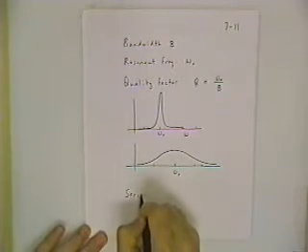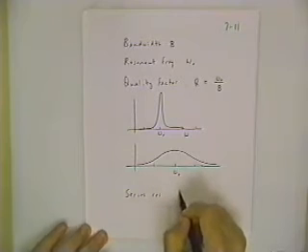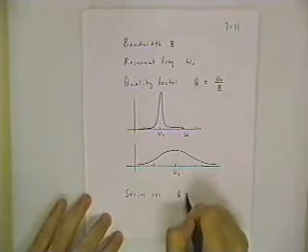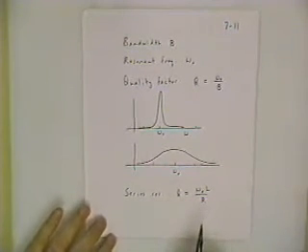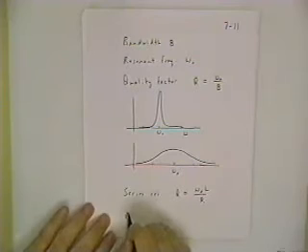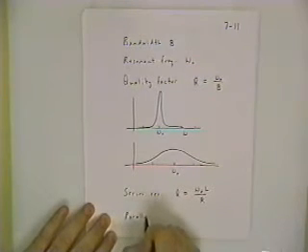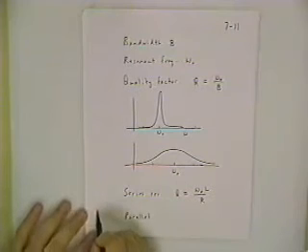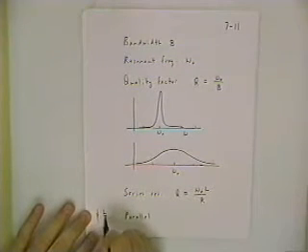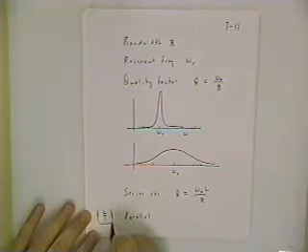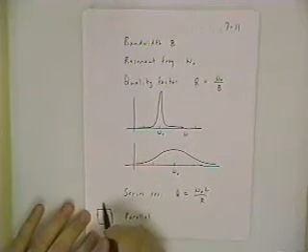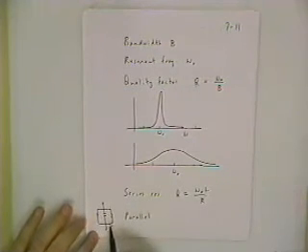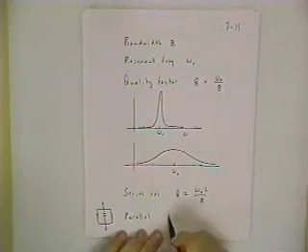For a series resonant circuit, the quality factor reads omega naught L over R. Now we can have the same sort of arrangement of parallel connections, and all you have to do is imagine connecting a resistor, in fact I'll sketch it here, resistor, capacitor, and inductor all in parallel, to perform this same resonance function. So you're comparing the voltage applied across these nodes to the amount of current going through it. It'll have the same resonant behavior. The only thing is the quality factor changes.